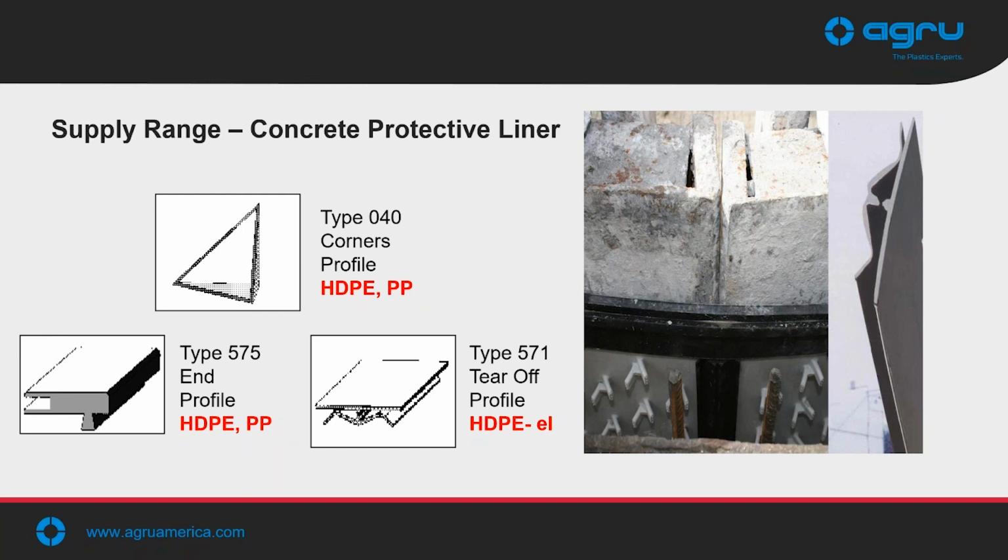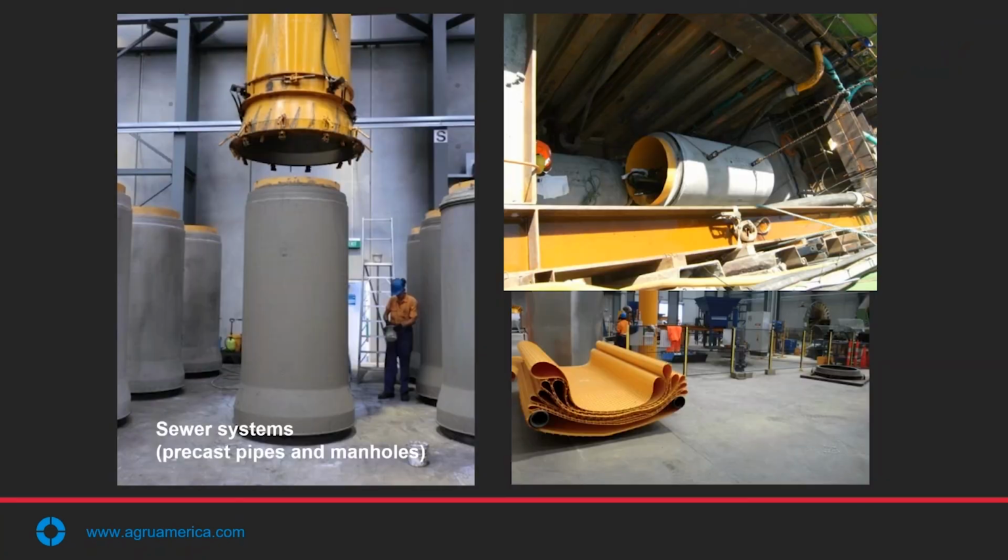When the material is cast, the face of the tear-off profile, just as it's described, can be torn off. And this profile is made out of an electroconductive polyethylene material. So the backside of the H profile, the curvy side, is left within the concrete. So when we weld our sheet together, because that piece that is back in the concrete behind the weld is electroconductive, we can spark test or holiday test back to that without the need for a copper wire.